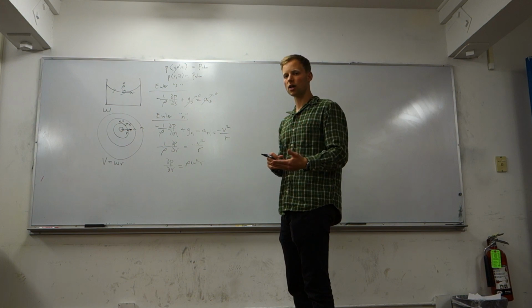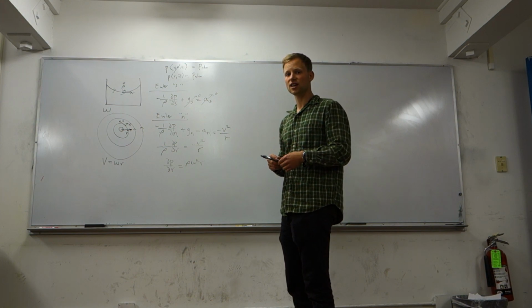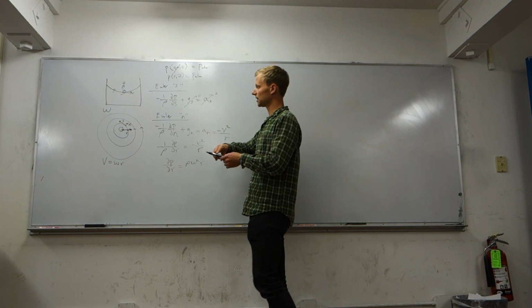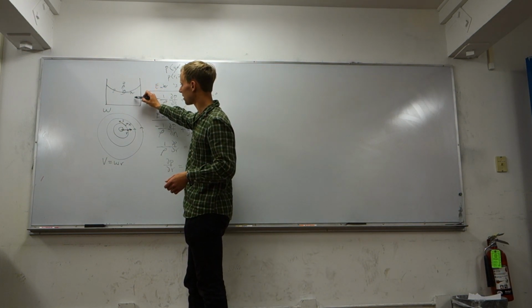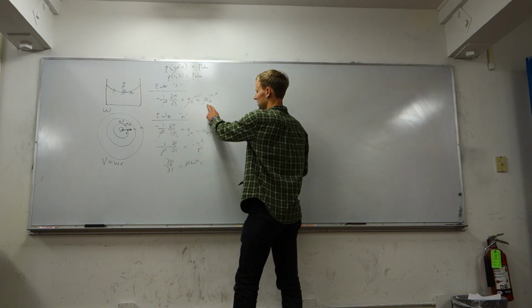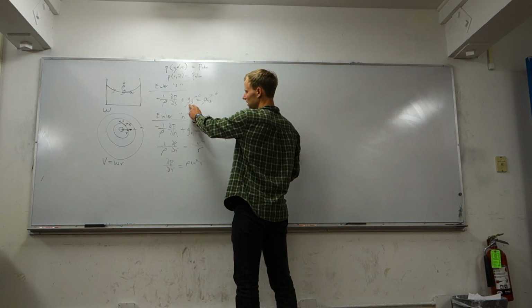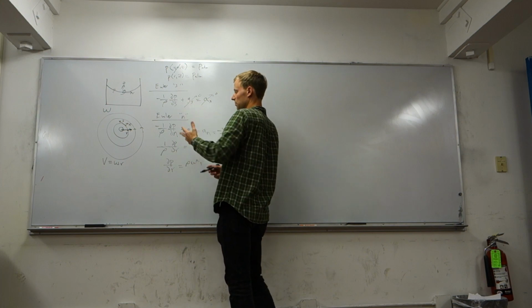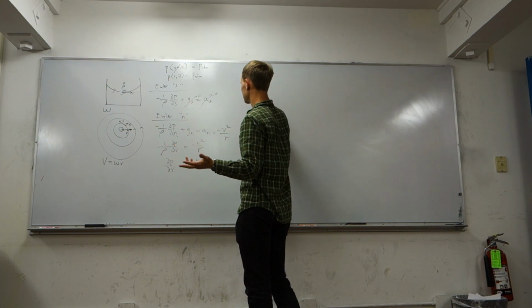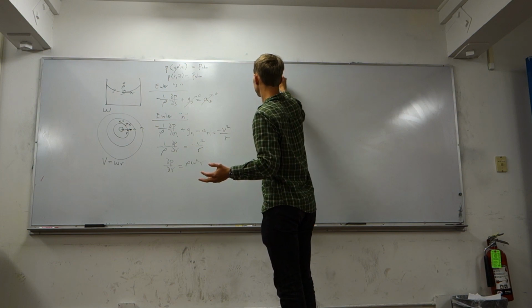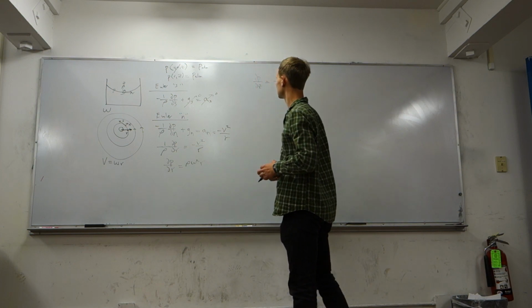You can think of it as an Euler equation in the z direction, or you can use Euler's equation and think about a streamline that's dropping from the free surface down to some distance z below the free surface. So the right side is 0. Now you cannot neglect the g component. So g dotted with the s direction is going to be g. And so we're left with just a simple dp dz is equal to negative rho g.